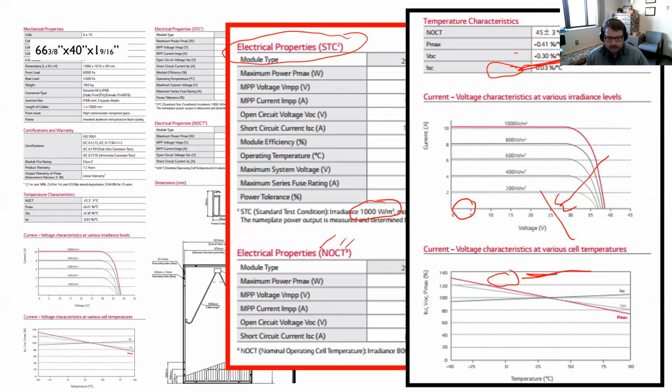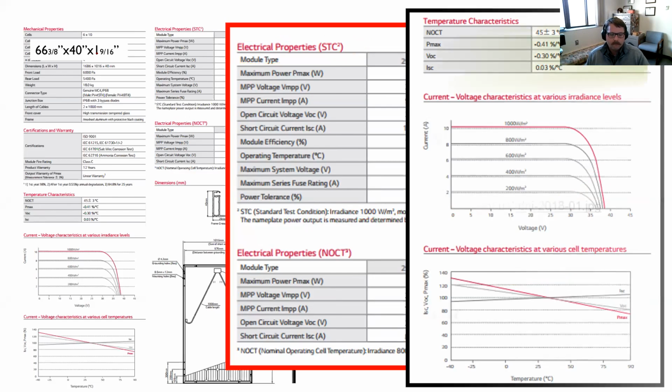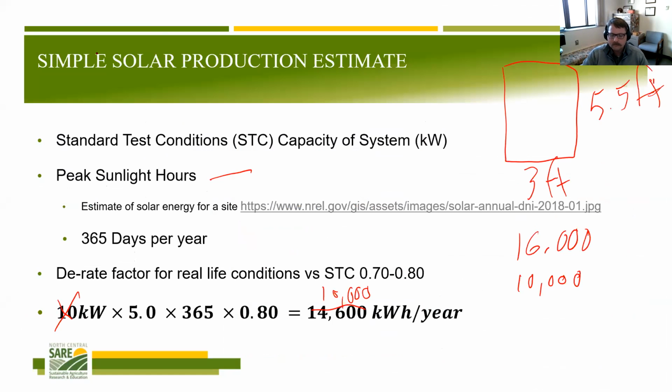Yeah, and that number changes all the time in terms of the overall dimensions. But essentially, to get to David's question, you could take your specs for that 300 watt panel, if it's 5 by 3, figure out how many square feet per panel, and then how many panels you would need. If you have a 10 kW system, you just divide by that, and that's how many modules it would take. Then multiply the number of panels times your square foot per panel, and that would give you the overall footprint, whether it's on the rooftop or the ground.